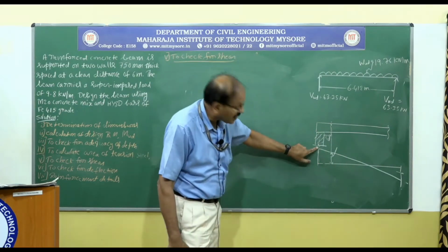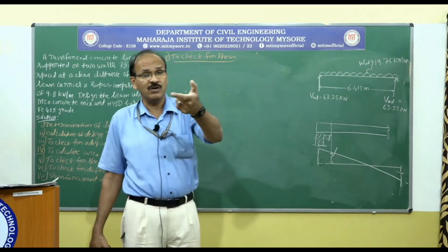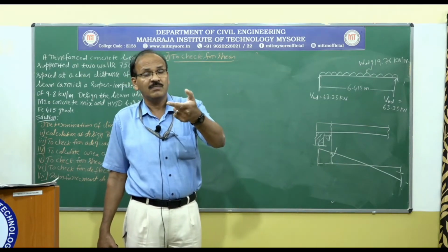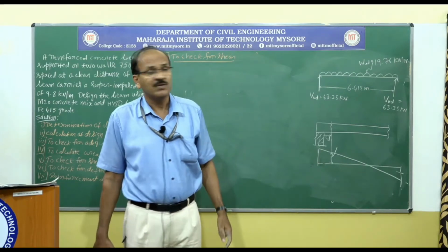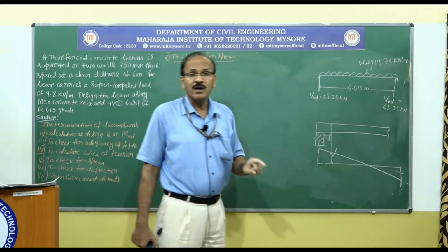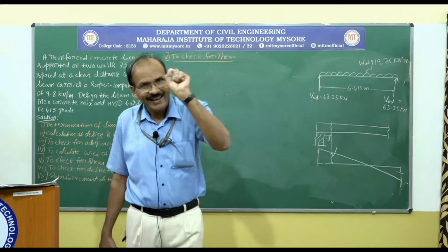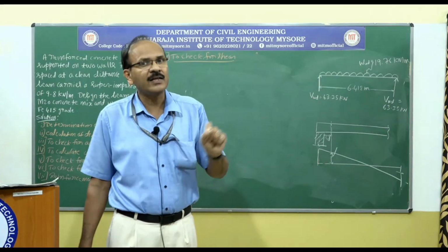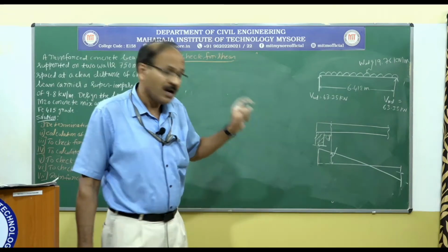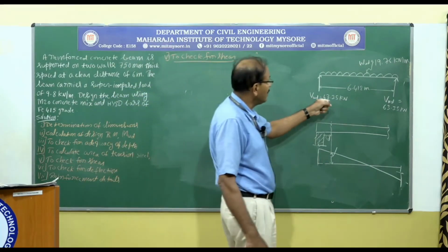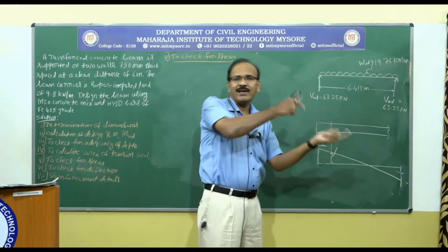Because I am taking a higher value of shear, I am going to be more safe. I am committing an error in calculating the exact shear. Instead, I am taking the shear towards a higher value.